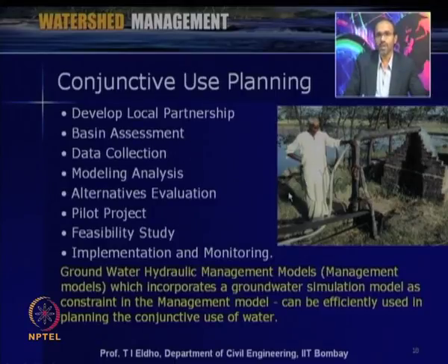We have to see what the surface water availability and groundwater availability are, and then how much the demand is. Then we have to collect various data like hydrogeological aspects, soil related aspects, and hydrological data. All those things we have to collect, and then develop appropriate models, as I mentioned.